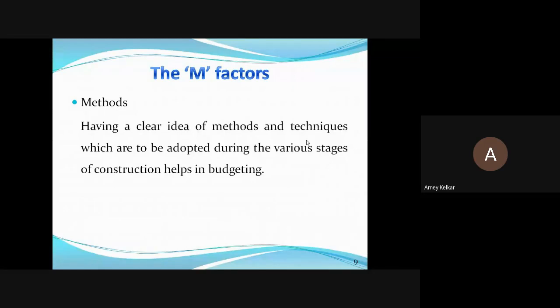Many times you find waterlogging in some areas, and in some areas you don't. So where you find or anticipate waterlogging, you have to be prepared with a method for dewatering. This is what you mean by methods, and finances will be required. Suddenly you have done the excavation and your pits are full with water, or the water table is very high, and as you excavate, water oozes out of the soil. Then you realize that you have to pump out this water, make the pumping arrangements, and do all that work. It causes delay as well as increases your project cost.